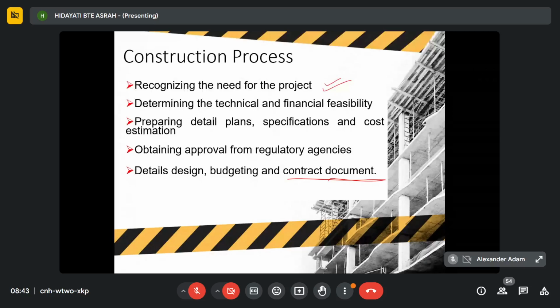the tendering. Okay, tendering, project offer, and construction work. So tendering here is a process for getting a contractor and agreeing on the price. It's the process you get a contractor. Which contractor you select, to give that project, to execute that project, the construction project. So it is a process where the client or employer will invite the contractor to place a bid for the construction work, and their bids are usually based on the tender documents issued by the client. Okay? So the selected contractor will be given the project offer to do the construction work.